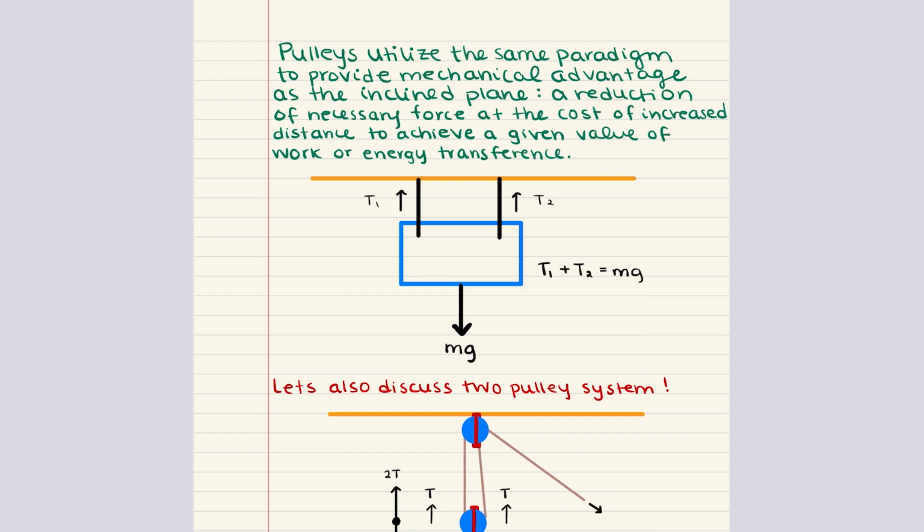The pulleys distribute the load across 2 segments of the rope, meaning each segment carries a portion of the load, reducing the amount of effort required from you. So in this case, the effort required is half the load, so lifting a 100 Newton load only requires 50 Newtons of effort, even though the total weight of the load being lifted remains 100 Newtons.